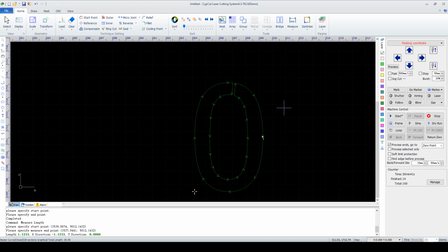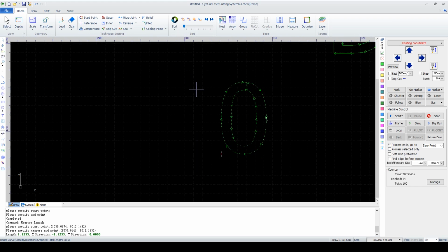Now let's come to the last feature. If we don't want parts to get automatically optimized when input, click Manually Optimize. In the drop-down menu we have this break grade, which is used to cut up the inner waste so as to avoid it going up and getting in the way of the cutting head.